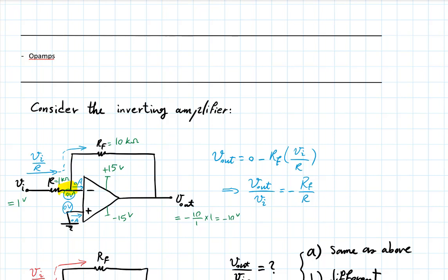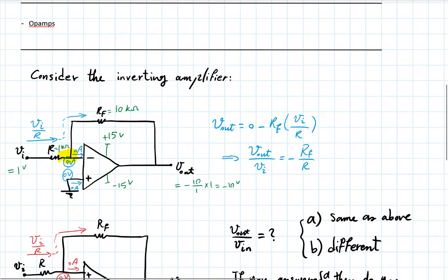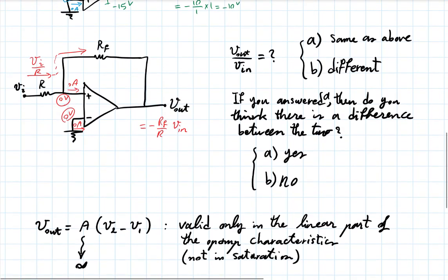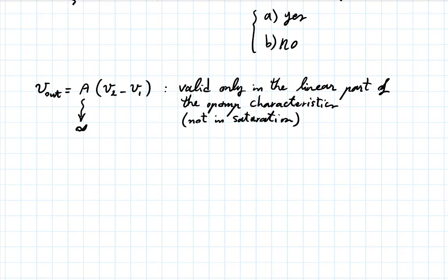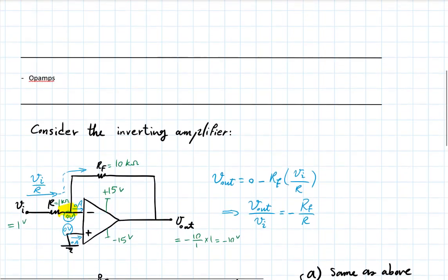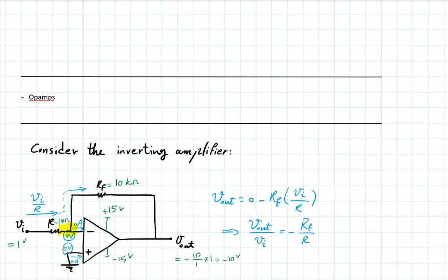Now imagine the opposite happens. Imagine momentarily that you have a negative noise that draws down the voltage of the highlighted node momentarily. Then V1 goes down, the op-amp wants to increase Vout. An increase in Vout, through this path of voltage division between these two resistors, will lead to an increase in the voltage of the highlighted node, and again will stabilize things back to where they were.